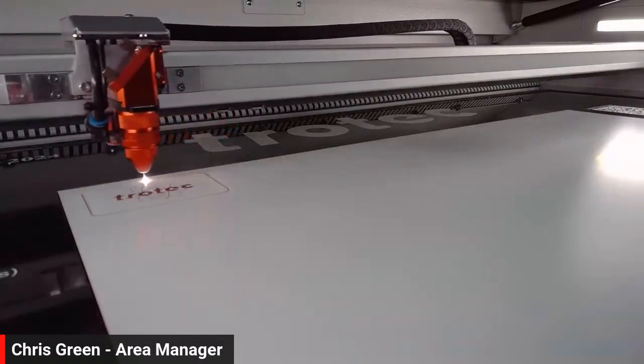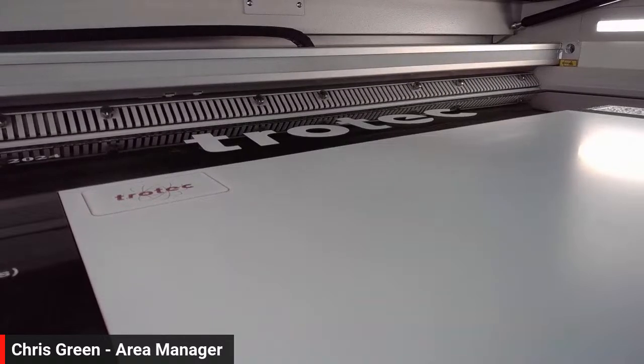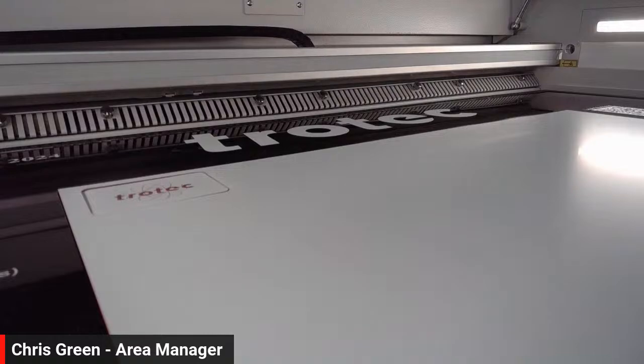So obviously if you're just doing a one-off, maybe it's not so easy, but if you're really setting up to do any kind of batch work, it really is worth making sure that your extraction is set up properly. It's probably one of the most important things after the actual laser system itself, to make sure you have properly set up extraction. Exactly right, and it's one of those things that we do talk about quite often. You can never overspec extraction. The more we have, the better. It really does help with a cut and help the material stick down.